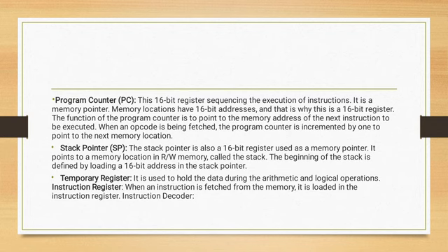Next, stack pointer. Stack, which I have already discussed, is a kind of storage container, from where we can retrieve or store data from a particular register into arbitrary address locations. This is also a 16-bit register used as a memory pointer, and a particular technique is used in a stack. This is called the LIFO technique, last in first out. The beginning of the stack is defined by loading a 16-bit address in the stack pointer.